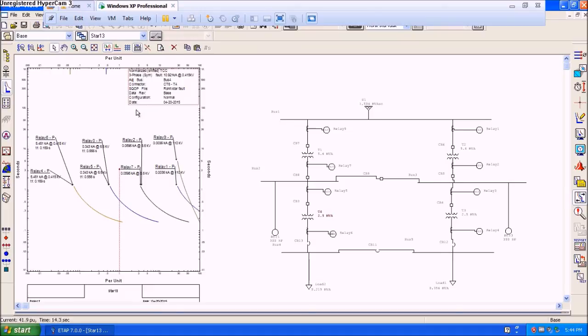Another concept can be explained by this. Suppose a power surge is there, then the relay need not trip unnecessarily, because it will affect the operation and efficiency. So we will provide a certain time lag after which the relay should operate. Suppose the power surge is there, then for a certain time the relay will not trip. So the power surge goes on, and it will not affect the power system. So we can increase the efficiency and stop unnecessary trippings. That is our concept, and we conclude from here. Thank you.